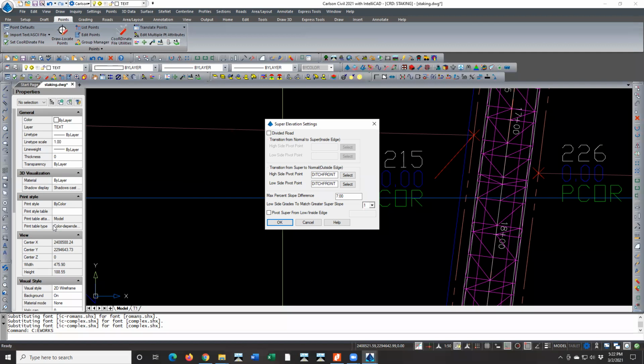Well, and I may have had 3. They told me the design originally was 4.4, and then they said no, do 3, and now they're saying do 4. So we need to do 4 there. So basically, in that 100 and some odd feet, the whole road was at the same cross slope, at 2%, and then it went to 4%.